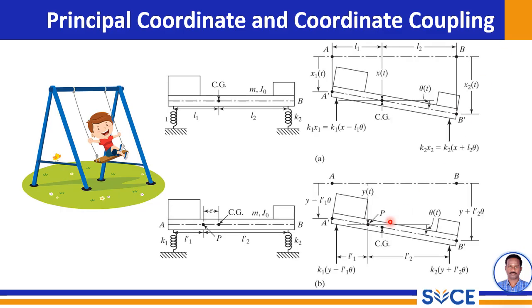Now let's delve deeper. These two figures, figure A and figure B, are with respect to a lathe. We are going deeper and analyzing the motion of this lathe. Figure A presents a system where a rigid body is suspended by springs. This could represent a vehicle suspension, or even a building foundation. Here it is a lathe with its legs. The legs are modeled as springs, a mathematical model.